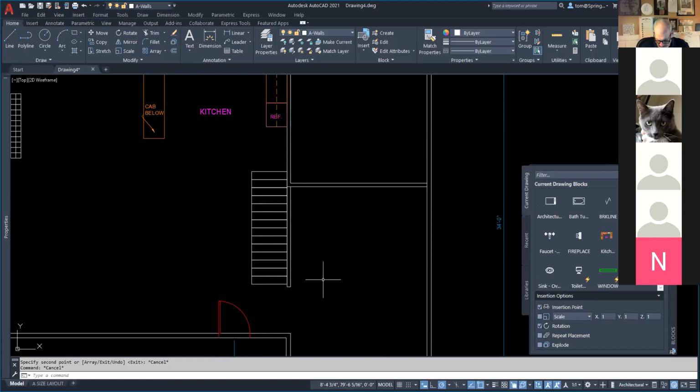Yeah, exactly the same. Okay, so now to make your break lines in these, once you've got your stairs in here, and by the way, it looks to me like the opening for the stairwell, the opening for the kitchen, is pretty much going to be 3 inches off the end of the stairs. So I'm going to go a line. I'll go 3, just so it's clear. Okay, 3 inches over, and I'll just go there like that.